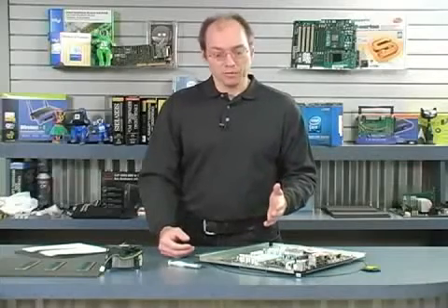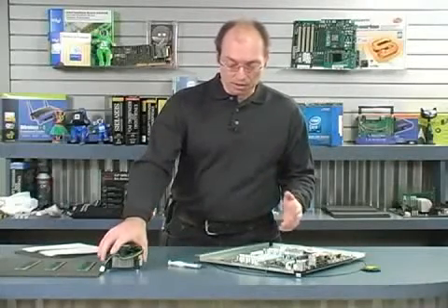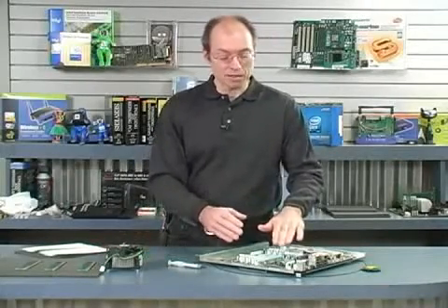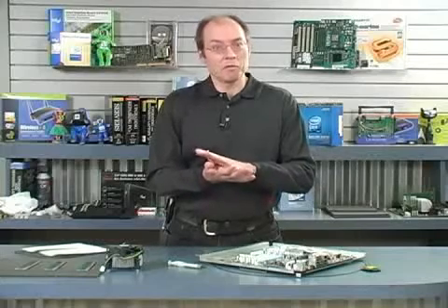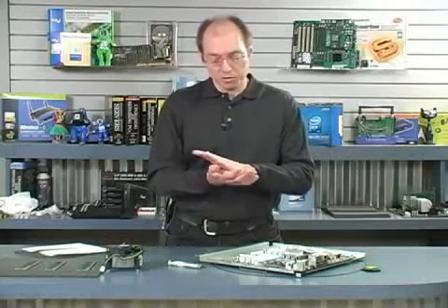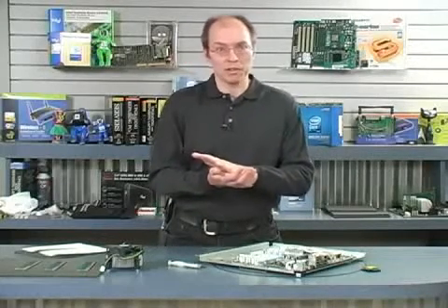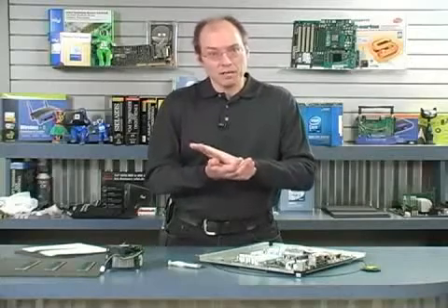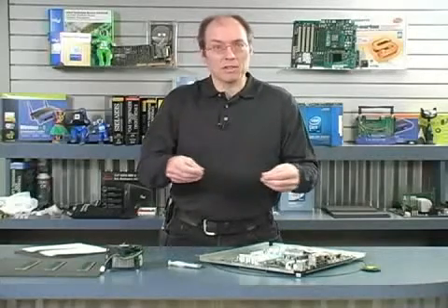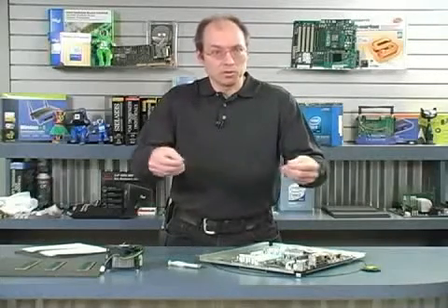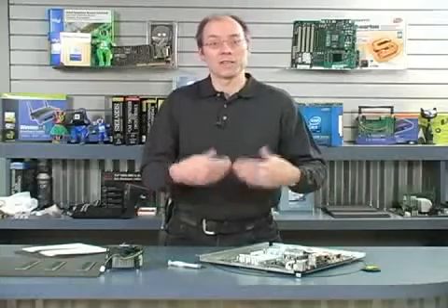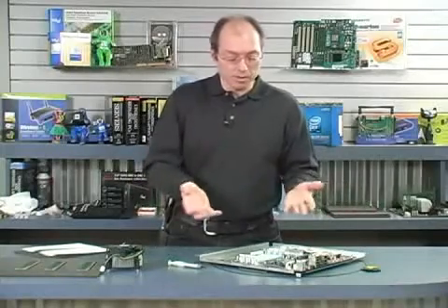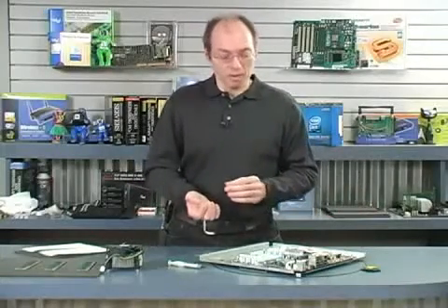Now, pump out refers to the fact that as the heatsink sits on top of the processor, there is slight movement due to just different thermal coefficients of expansion, contraction, vibration, and eventually this movement kind of pushes the grease out. It kind of extrudes, it oozes out from between. So eventually, there's an insufficient amount in there.